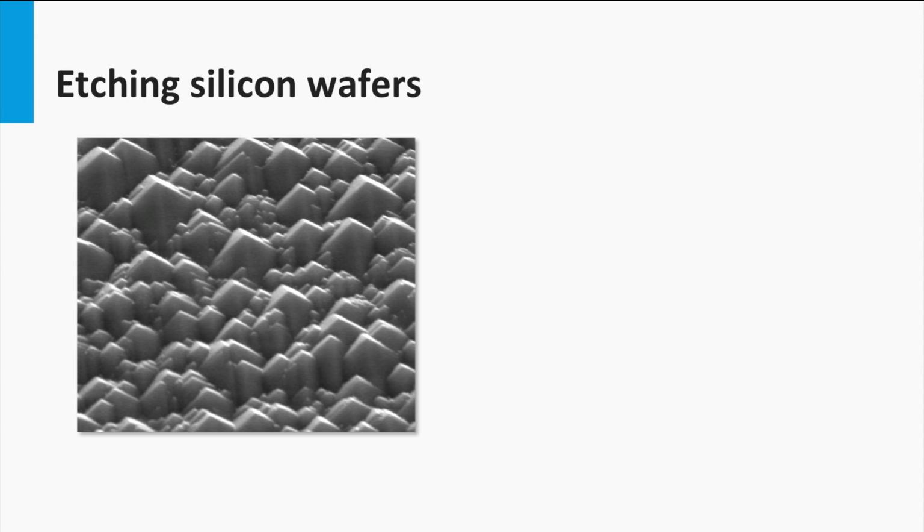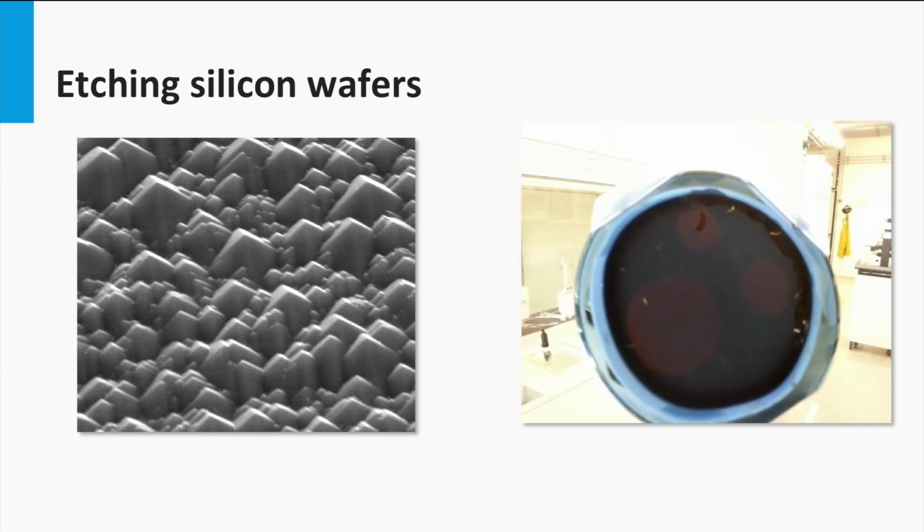The texture on the wafers can be realized with wet etching approaches. Here you can use an interesting property of the 100 surface. This anisotropic etching can be used when etching a crystalline silicon wafer with an initial 100 surface orientation. Etching of such a wafer leads to textured surfaces with a pyramid structure having only 111 oriented surfaces. In this picture you can see such a textured surface of a monocrystalline silicon wafer as processed at the DEMO lab in Delft. Using such etching procedures, it is even possible to have a silicon wafer looking black, as shown here in the second picture.